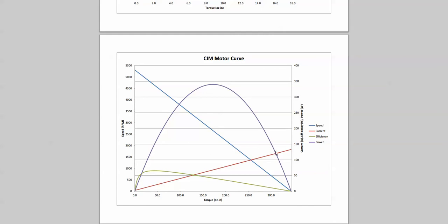I said the load that your system is putting on the motor because there's a misconception, again isn't the right word, but it seems like a lot of people think they control what's going on with the motor, and that's really not the case. All you control is voltage, and then the motor will try to move, and whatever torque it experiences will determine what speed it is going, the current draw and such. So you cannot will your motor to do anything else, but you do get some effects by using a control loop to increase or decrease voltage. But voltage is all you're controlling. You do not get to pick your point on this curve in real time for a set voltage. If you're at 12 volts, the torque that the system has experienced purely determines the speed you're at, and therefore the power and efficiency and all that stuff.